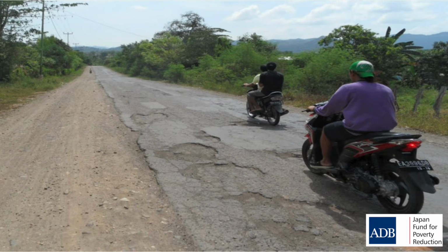So if you're going to manage speed with bumps or devices that narrow the road, they need to be well lit, because at night, if a motorcyclist at speed hits that, it's very dangerous. They need to be well lit, they need to be line marked, they need to be obvious. You can still use them. They are great devices for pedestrian safety, for vehicle safety, and they are good for motorcycle safety because they will slow down.